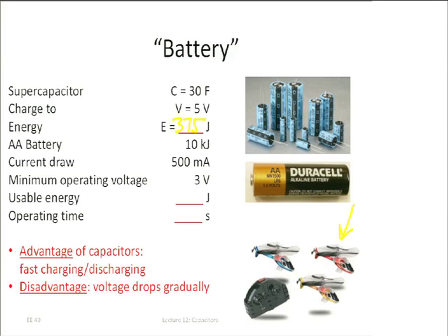With a battery, is that also the case? Yeah, for most batteries, it's not the case, right? You use a battery, and only when it gets very close to the end of its life does the voltage start dropping. So as a function of time, if you draw a fixed current, here's the voltage, and the voltage of a capacitor is simply going to look like this, whereas the voltage of a battery is going to look something like this.